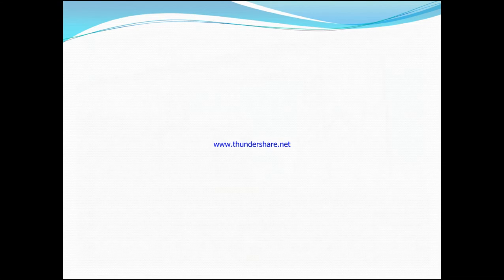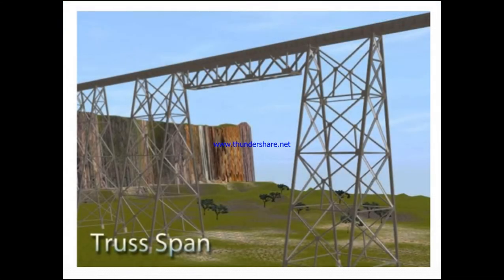If it is 2D, it comes under plane frame. If it is 3D, it comes under the space frames. This is a truss span. Transmission line towers will be similar to this structure. This is a 3D frame. It is a rigid jointed frame because it is not connected by pin joints.